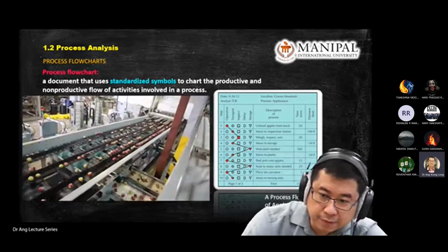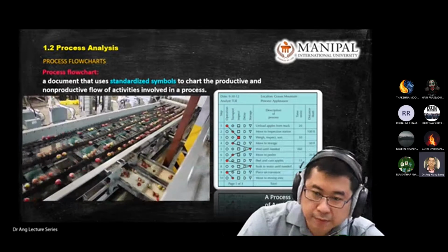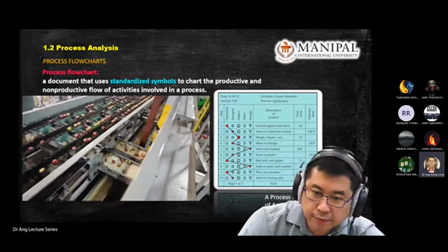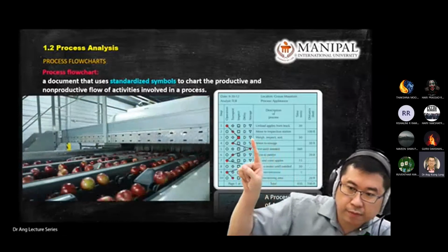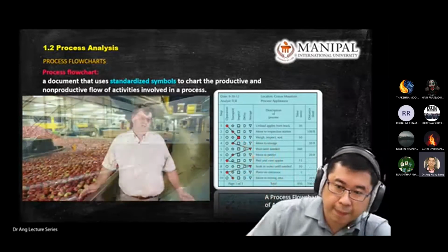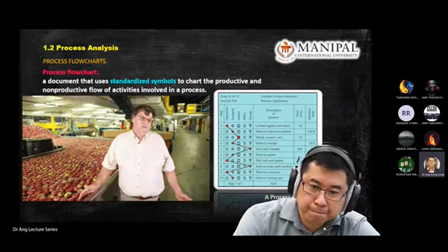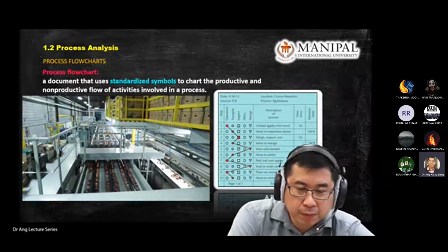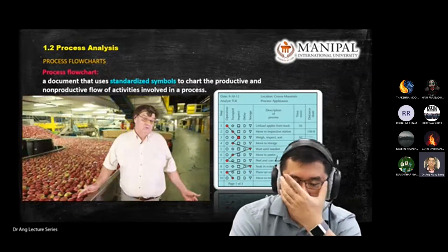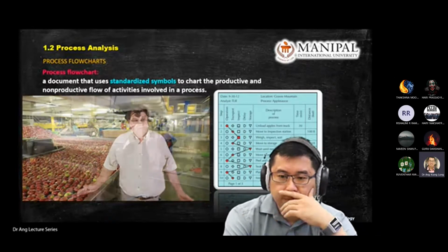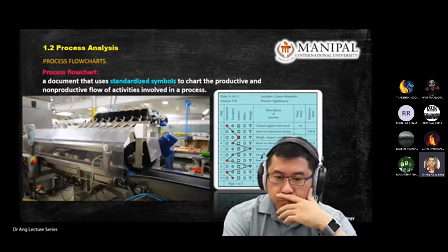So as the apples come over the sorter, it knows where it is on it. It measures it by weight, it measures it by optics, by size, measures the color on the fruit, so how red it is or how yellow it is, and it also takes a look at it and determines if it has defects or it doesn't have defects, and then sorts them according to that and puts them where we allocate it, either for fruit to be sorted to process or fruit to be sorted to the fresh market to go into a bag or a tray.